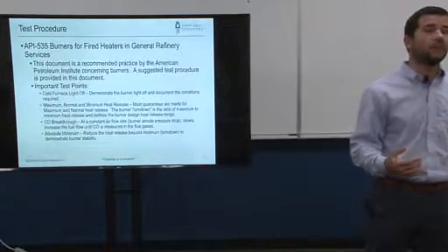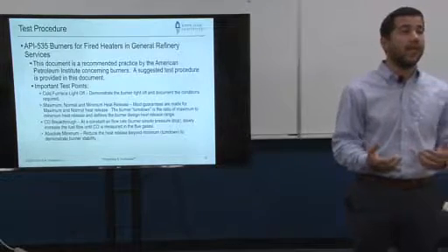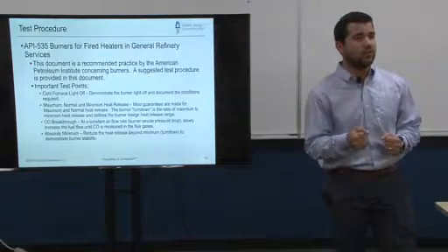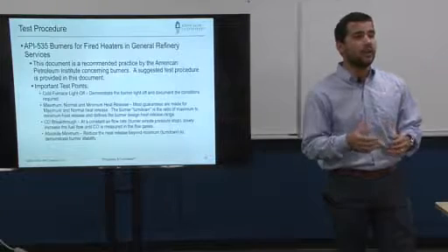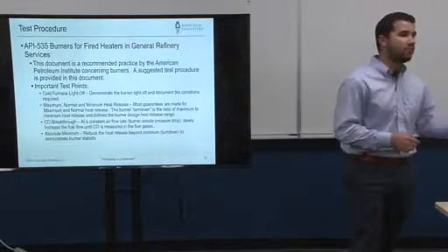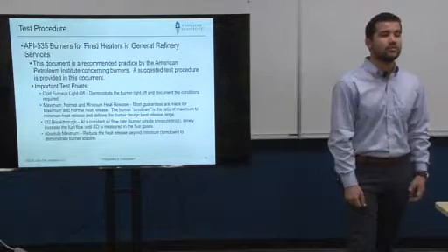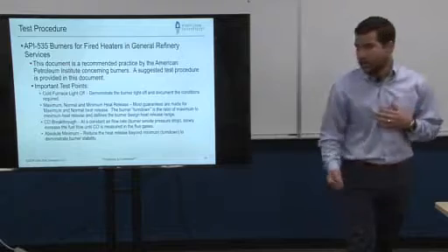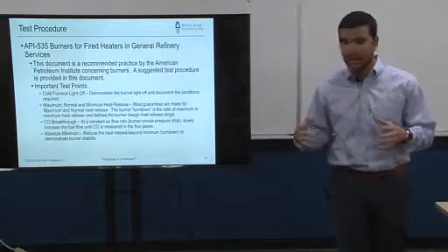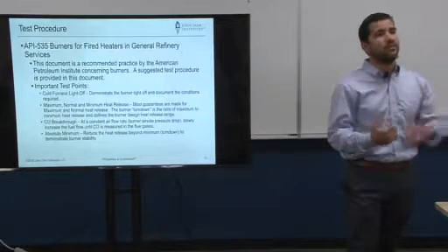Some customers like to look at other things, such as, can we do CO break by air? That means, can you close the burner opening until the burner literally runs out of air? So there are a lot of flavors of testing, and those are typically driven by the customer. I know what I'm looking for, this typically covers it, and then the customer has their own requirements too.